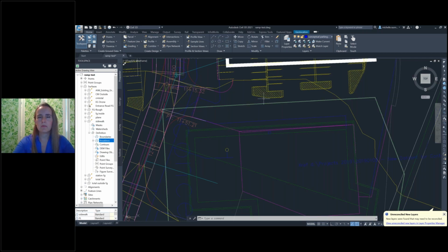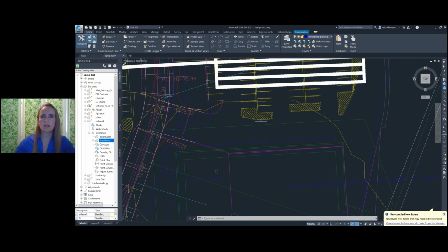And then I'm going to pretend that my ADA ramp needs to come off of here so that they can cross the parking area, this drive area, and get to these parking spaces that would probably have some handicap symbols in them, so that that's our handicap parking. And then once I have this first ramp done, I'm going to have another one so that they can get to this. So maybe there's 2 doors here on the building, one at this point going straight out, one at this point going straight out to get to those ADA parking spots, those handicap parking spots.